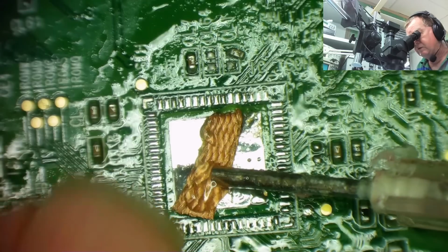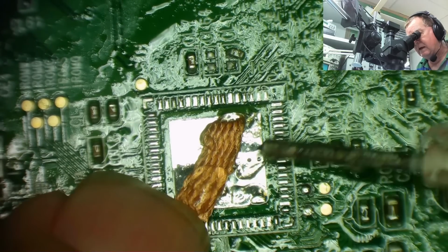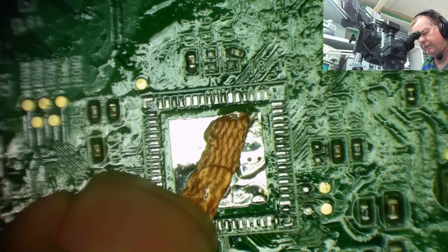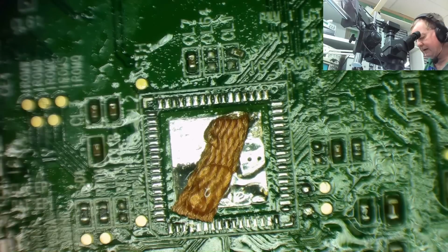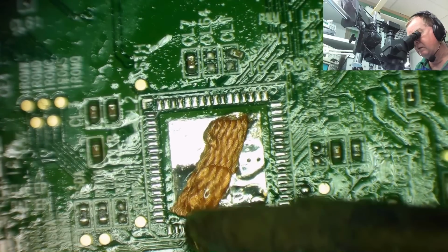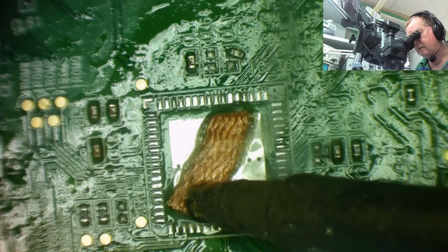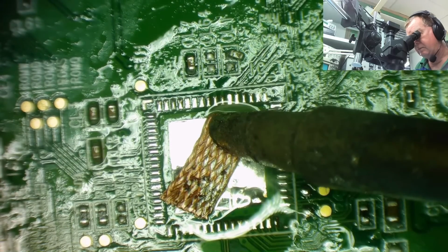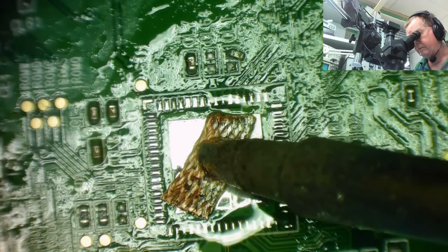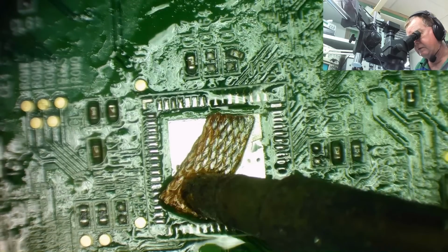And once again, I want to just clean up this centre pad. If it's raised too much, it'll kind of hold the chip slightly off the board, and then you won't be able to get it to sit on the legs. You won't get it to solder. That's the problem here. So again, notice that alcohol didn't have any effect. It's not a problem. Got enough heat in to move it.